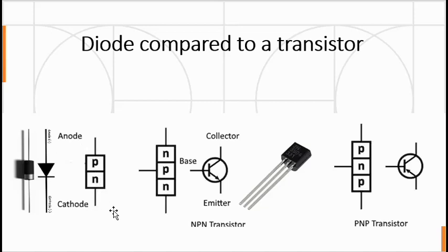So some guy looked at this and said, well, what happens if we add another doped material, an N-doped onto it, and we have two junctions, we have an NPN. Well, when they did that, they realized that they had some special characteristics. They called it a transistor. So we have our collector, our base, and emitter. And that's an NPN transistor. Transistors look like this. There's the 2N3904. You've seen that in the lab.